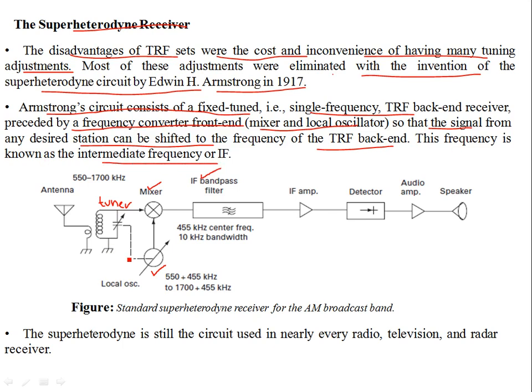Okay, so what happens is, once you select the center frequency, let's call this the desired RF frequency. You have a desired RF frequency over here. This is going to be mixed, and this mixer, by the way, could be a balanced diode ring mixer, or it could be a non-linear diode mixer, a JFET mixer, whatever. It could be a Class C mixer as well.